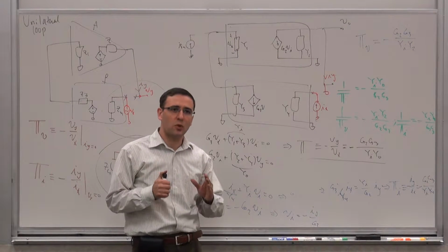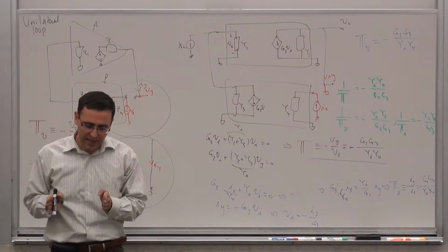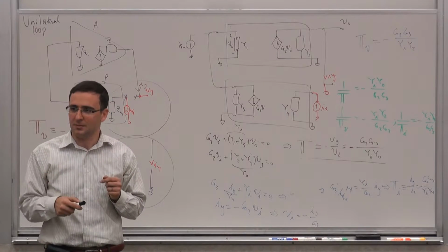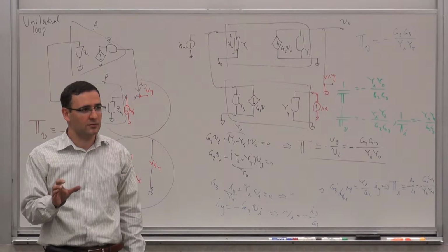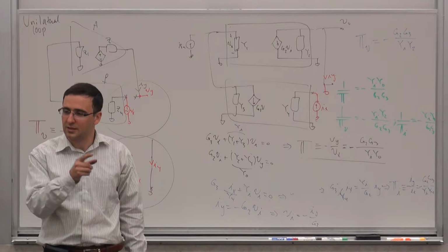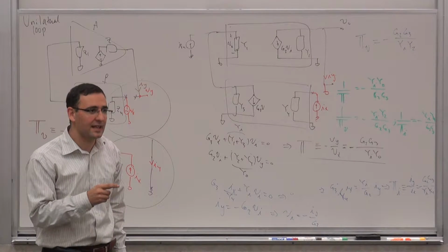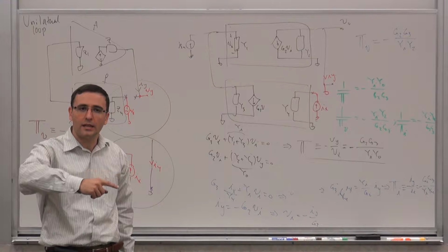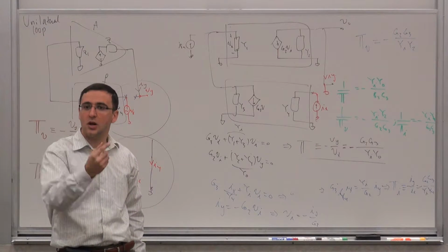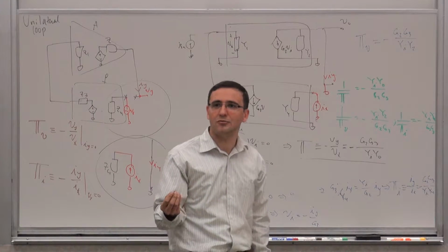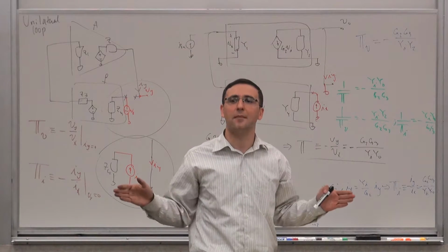Right, so now, what we did is that we looked at the unilateral system, and we saw that you could generally define a loop gain that was invariant of a single loop if you had a single loop. And it basically had the property that you could calculate it anywhere. We also saw a good way of calculating this, which made it easy not to think about the loading effect.